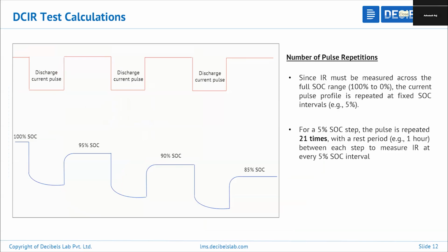The polarization effect is basically this: in a battery, lithium ion migrates from the cathode to the anode and from the anode to the cathode during charging and discharging. Some processes are associated with the electrode materials, and those will be associated with your ohmic drop. Polarization covers the processes that take more time, like diffusion. Whatever resistance is associated with diffusion will be assigned to the polarization effect.